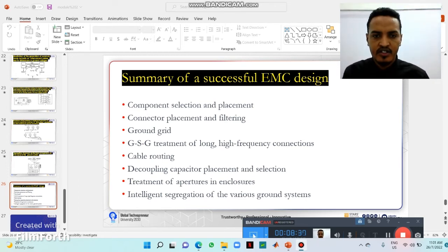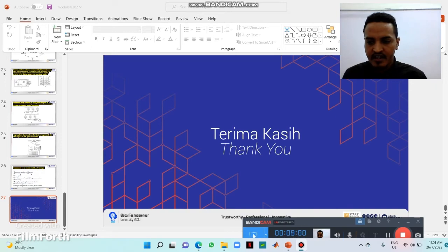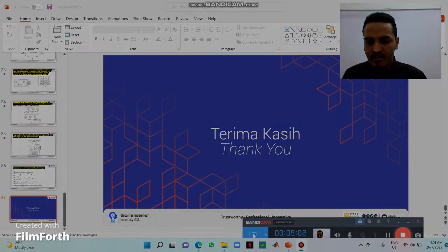Our project summary of successful EMC design: component selection and placement, connector placement and filtering, ground grid treatment, long and high frequency connection, cable routing, coupling, capacitor placement and selection, treatment of enclosure, and intelligent segregation of the various ground systems. And thank you very much. Thank you to my tutor.